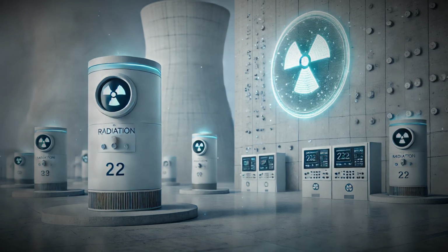The importance of radiation protection extends beyond normal operation. During refueling outages, when the reactor is shut down and spent fuel is handled, additional monitoring is used to ensure safe working conditions. Spent fuel is stored under deep water in pools that provide both cooling and shielding from radiation. Later, it may be transferred to dry storage casks designed with thick steel and concrete walls.